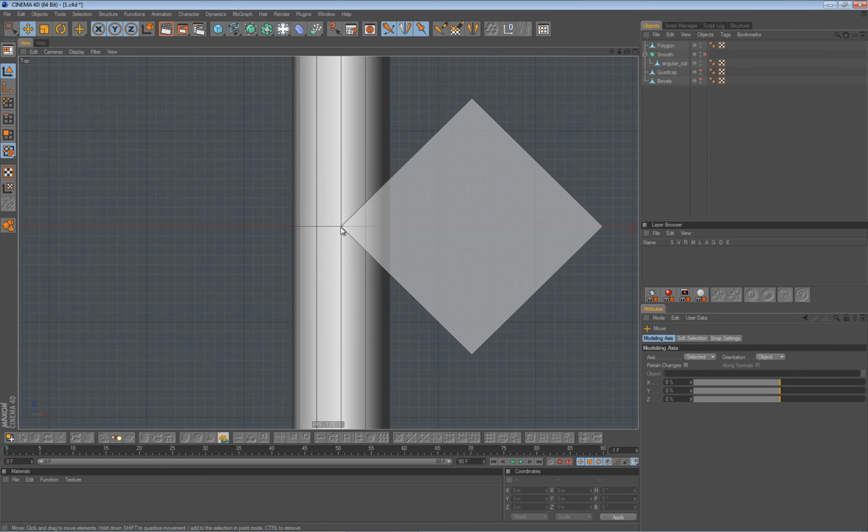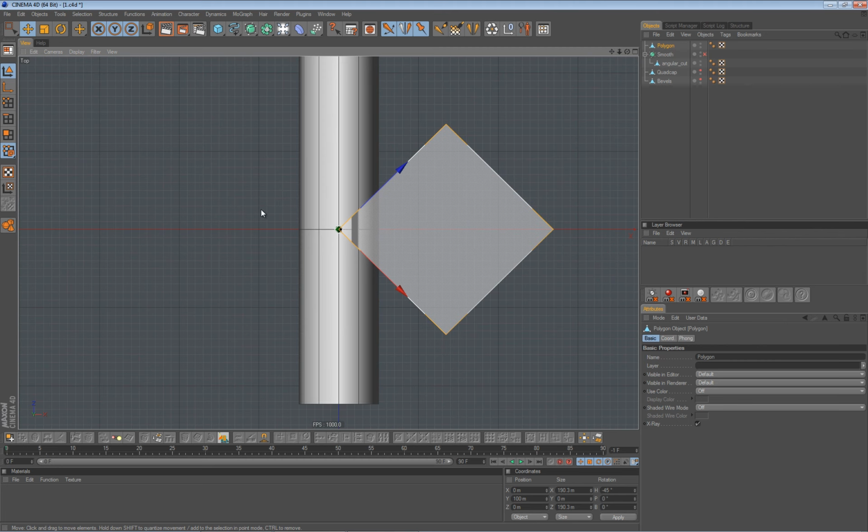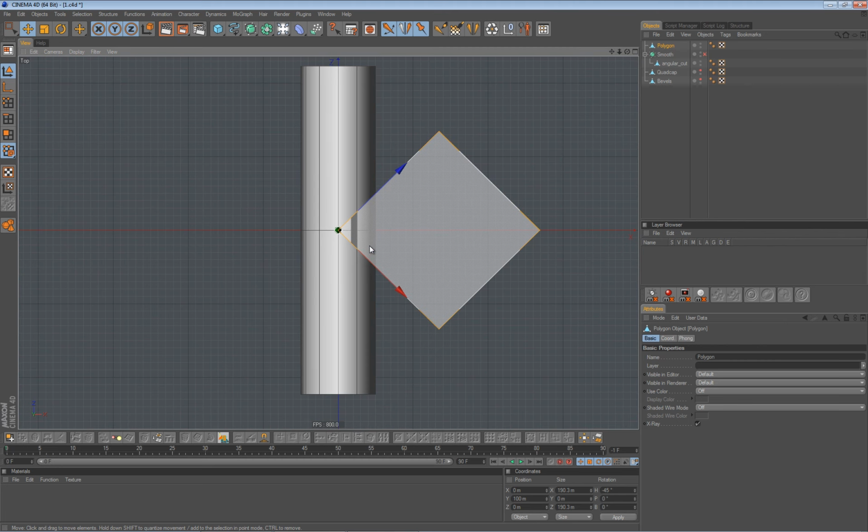So now, if I use my knife tool and follow the contour of this polygon as a reference, I will get exactly 90-degree extrusion. And the really nice thing is, if you want to extrude at a specific angle, you will type here that exact angle. So let's say we want maybe a 60-degree angle.